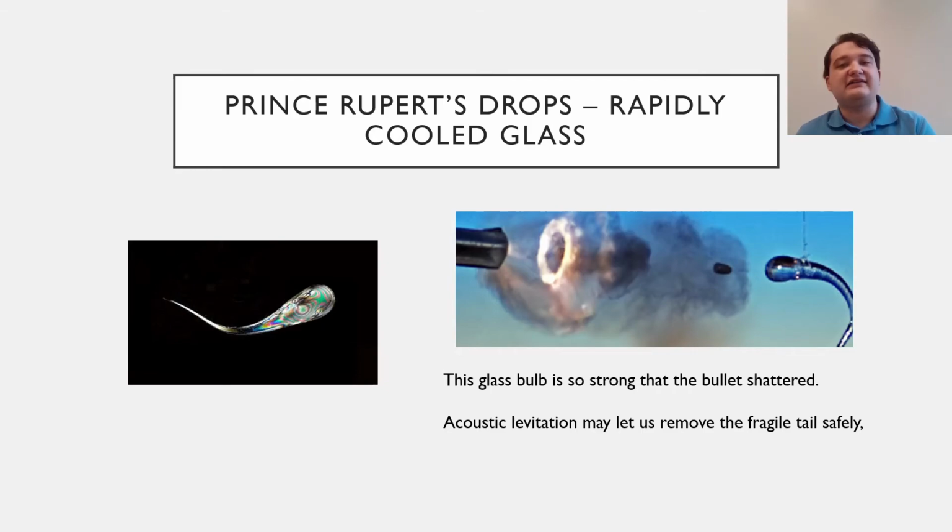One experiment that both I and Dr. Halston want to do one day is to levitate molten glass and rapidly cool it, in order to try and make the glass substantially stronger than it would be otherwise. To do this, we would need to melt the glass while it is levitating, which has several difficulties. The speed of sound changes with temperature, so the location of the notes and where the glass itself is levitating would change as it melted. We would need to find a way to keep the glass stable and levitating as this happened, and we would have to construct a levitator that can not only lift a heavy object like glass, but can also withstand the high temperatures.